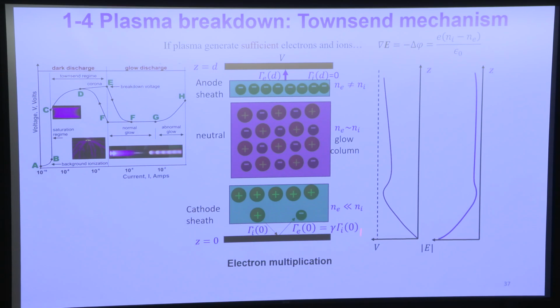And now you start to say, because in the neutral region, your electric field does not change. And near the cathode, you get a lot of positive ions. They create enormous potential. And near this interface, you get electrons attracted here. You get a potential decrease, and this is the perturbation about this charge distribution. Now, because you have more charge, they perturb the electric field, and you can see at the cathode, the electric field is so strong.